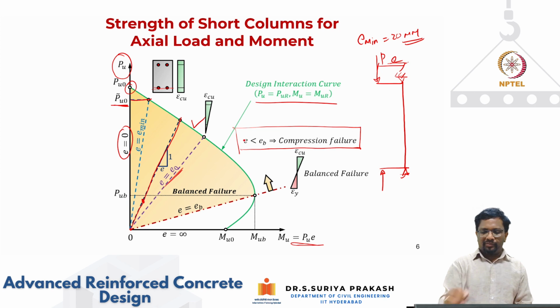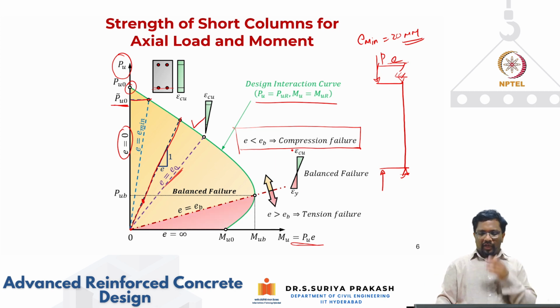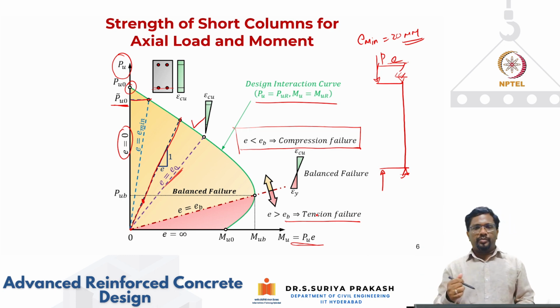So when E becomes less than EB, the column behavior will be dominated by compression failure. Okay. When E becomes larger, more than your balanced eccentricity, then you have tension failure. That means before the concrete at top reaches its compressive failure strain of 0.0035, your bottom rebar is going to yield.